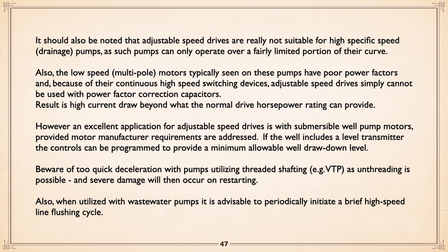Another thing with wastewater pumps: remember the thing that you have to worry about, solids falling out at low speeds? So it's generally a good idea at intervals, say 2 o'clock in the morning, whatever, that you operate a variable speed sewage pump at full speed so that you can flush out the lines.